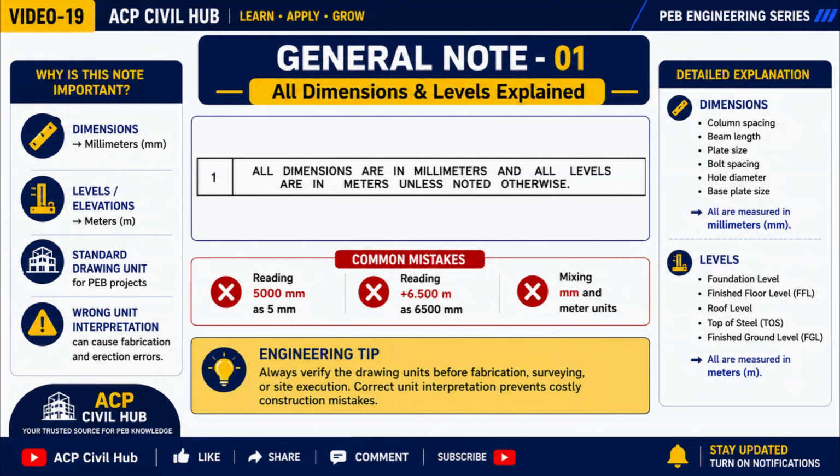Similarly, all elevation values such as foundation level, finished floor level, roof level, or top of steel are measured in meters. For example, if the drawing shows +6.500, it means an elevation of 6.5 meters, not 6,500 millimeters.